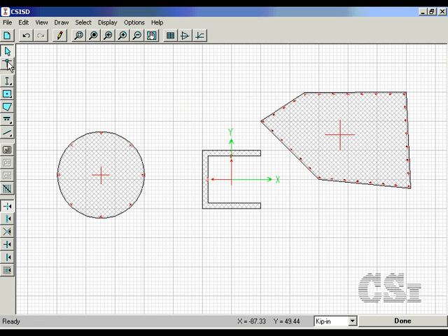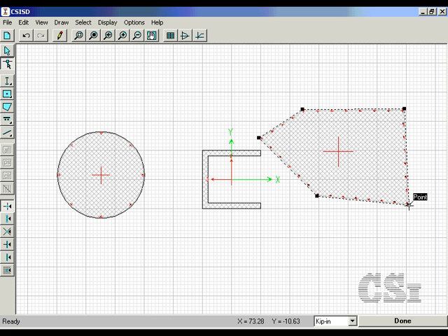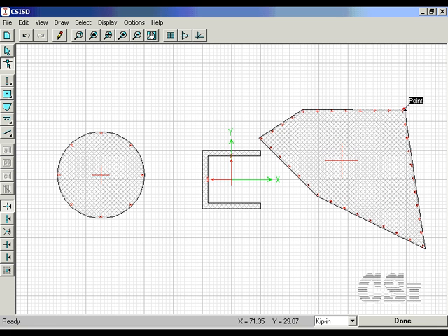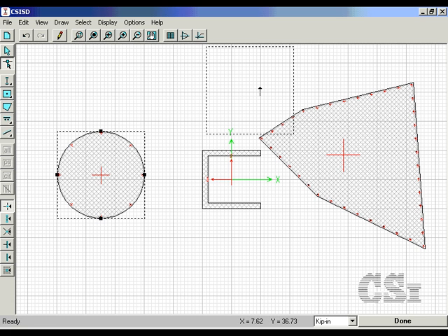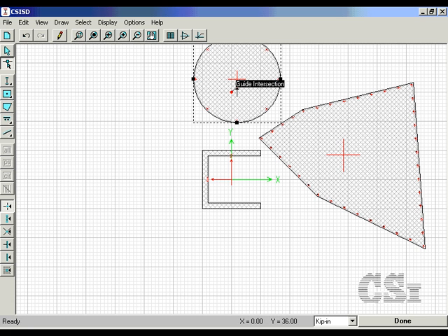The Reshaper tool allows you to move the shapes as well as to change the geometry of the poly shape by simply dragging or right-clicking on the corner points. At this point, it should be noted that all three of the drawn shapes constitute a single section, and though one of the shapes is steel, the Section Designer utility will calculate properties for SAP 2000 based on the equivalent base material of concrete. It should also be noted that the XY axes shown are local references only.